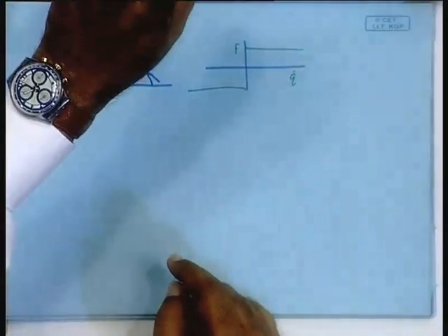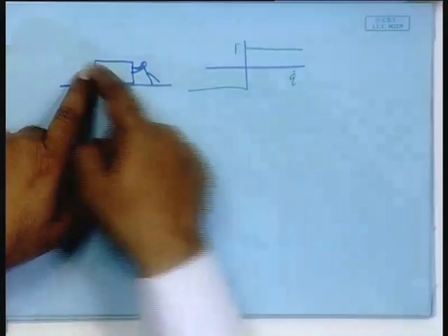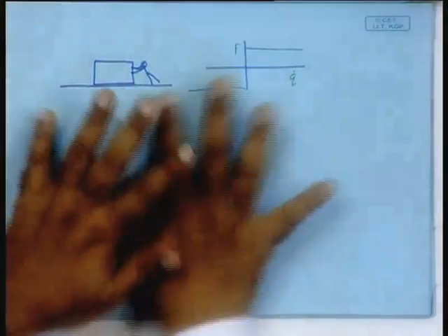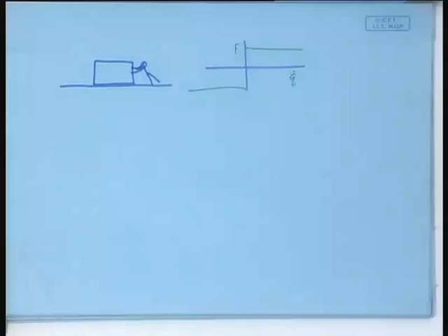What will we do then? The general technique is first assume that it is a linear thing, thereby what will happen, for example this one, we will write some kind of an R. If it had been a viscous friction, we will write R, we will write the equation that way, and then say no, my R is not a fixed quantity, it is a variable quantity which has dependence on this, then we can substitute that dependence into the equation. The moment you do that, the nonlinearity is represented, clear.